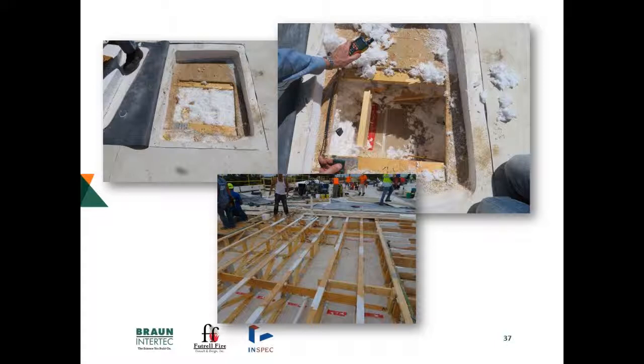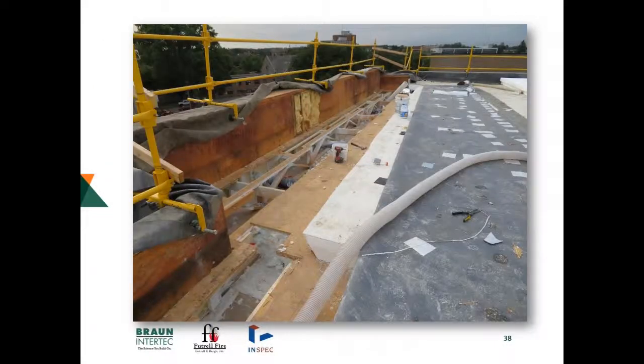And these things were then covered up each day, so you had a buttoned-up roof at the end of the day. The picture on the bottom was one of the more center areas that was opened up during construction, and it shows you just how much of that area was inundated by moisture that had to be obviously taken out of there, the materials taken out, and then remediation done to stop any mold growth. So this is more of the impetus of the roof replacement challenge at the perimeter, where you go in and pull back that membrane, take out that insulation, start cutting back a couple feet of plywood deck around the perimeter to reach down and get into that foam bridge construction work.